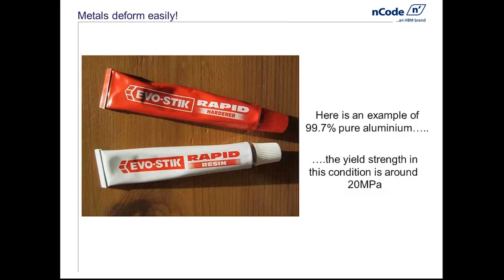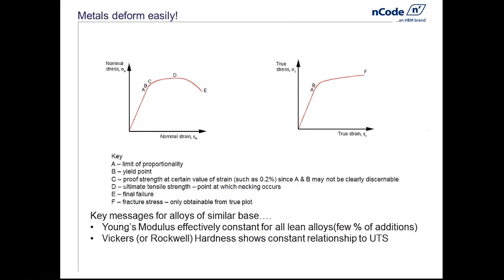It also shows another feature of metal behavior. When you bend it, and we always do this because when we flatten them in the wrong place, we then try and kink it back, it won't bend back exactly, and usually what happens is we put a little bit of low cycle fatigue in it, and the thing splits and some of the contents leak out. It's a pain, but that's life, and that's what metals do.